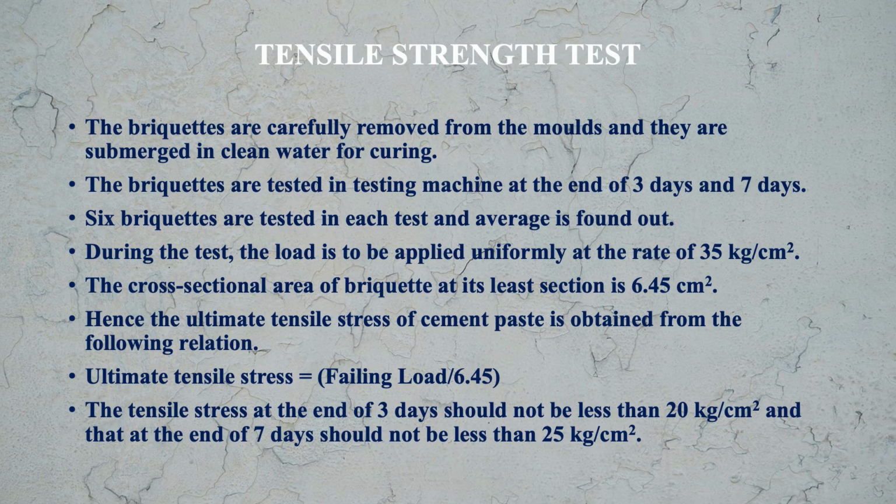Now the briquettes are carefully removed from the molds and they are submerged in clean water for curing. The briquettes are tested in a testing machine at the end of 3 days and 7 days. 6 briquettes are tested in each test and average is found out. During the test, the load is to be applied uniformly at the rate of 35 kg per centimeter square.